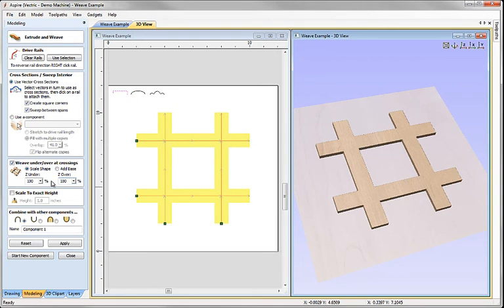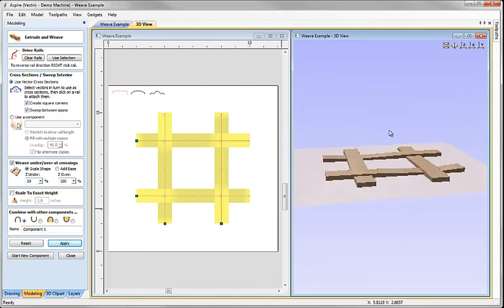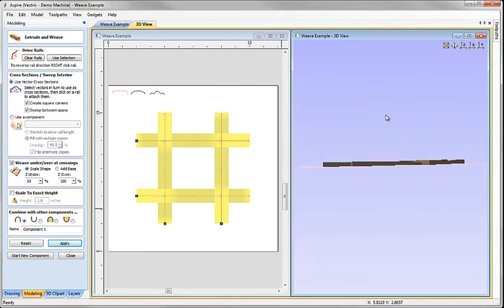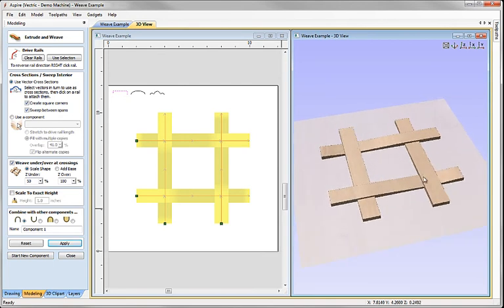If I want to change this, then I can come to Z under, I could enter 50%, hit apply, and now what the software is going to do is reduce the height of our cross section as it's extruded on the areas where it overlaps by half of its original distance. So there you can see that the top is level, but these areas are all going down. If we change that back to 100% and hit apply, it'll go back to as it was before.